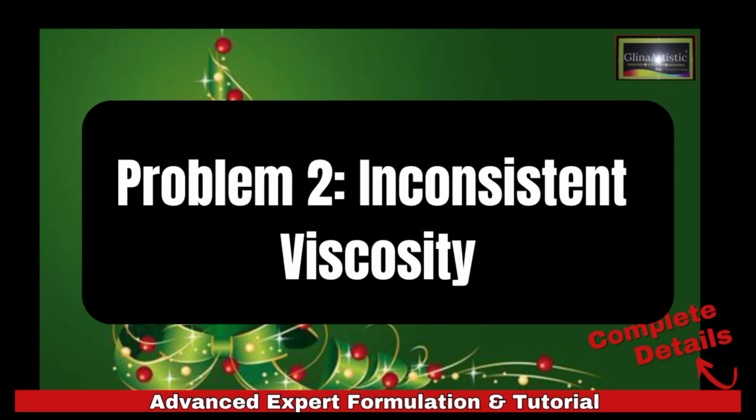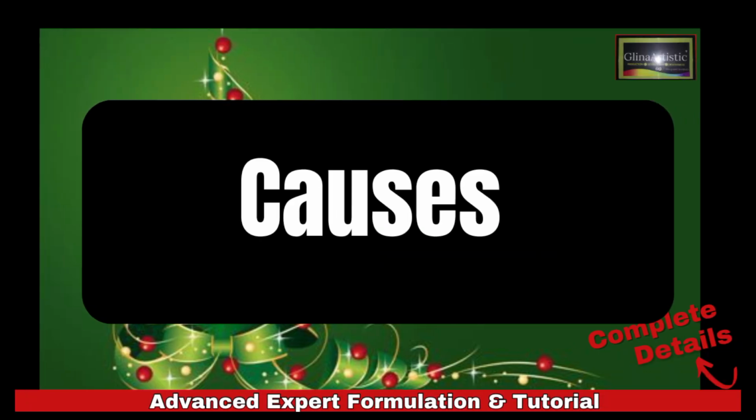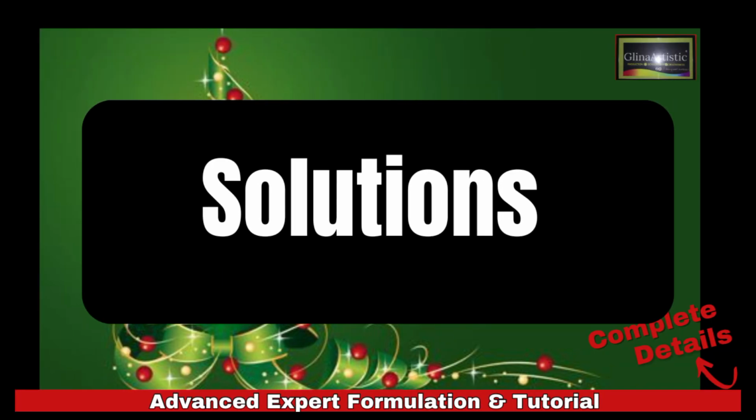Problem 2: inconsistent viscosity. So what are the symptoms? Paint is too thick or too thin. The causes are incorrect thickness or solvent reaction. The solution: 1. Use a viscosity meter to measure and adjust viscosity.